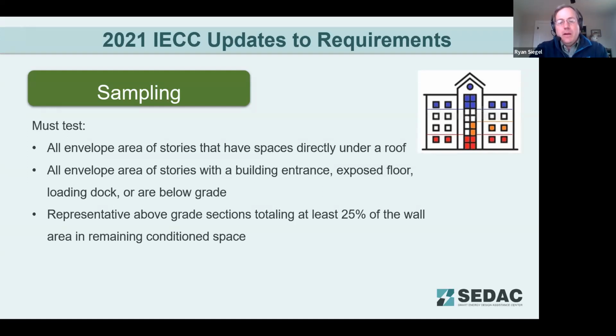However, understanding in a case like this, I'm likely to test an entire floor rather than trying to test a portion of a floor, because that's going to be rather difficult, understanding the limitations of your testing process and where your air barrier is. A partial floor probably is not going to have an air barrier of an appropriate integrity in order to actually do your testing. So again, this is showing the minimum testing that you would have to do, testing the blue, red, and orange areas.